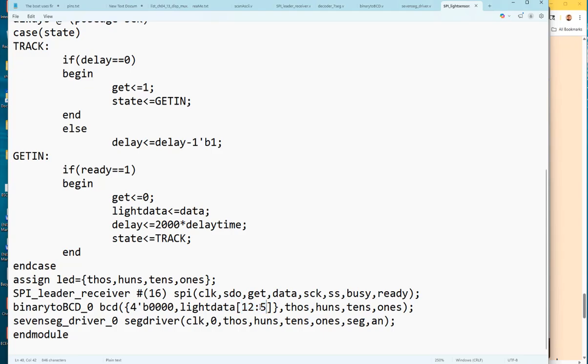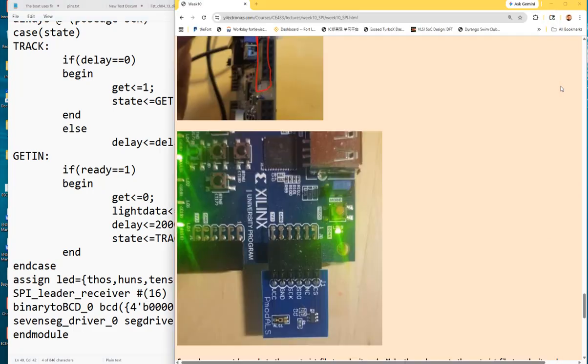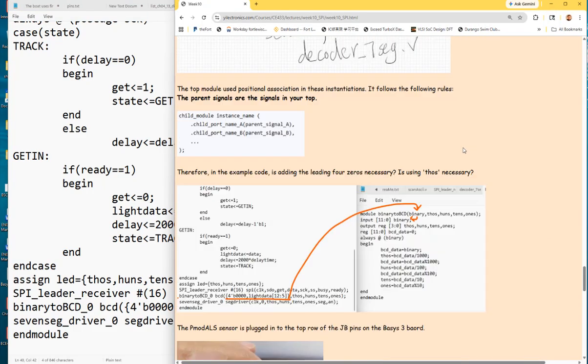By doing this, I don't know, interesting. If I overexpose it, I use my flashlight to actually shine on the light sensor, I'm reading 255 actually. I'm reading 255. Shouldn't that be 11 to 4? That's what I'm thinking, right? Because the ADC does say that it starts from the 5th bit, which is bit 4.